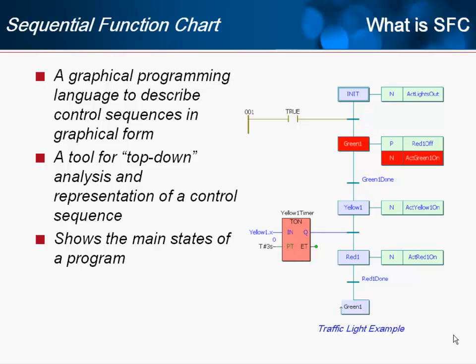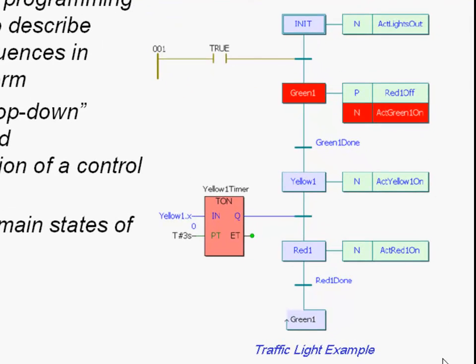You can see over here on the right, we have some SFC code for a traffic light controller. And so once you know that this is a traffic light controller, with SFC you really don't need to get too deep into the code to get an idea of how the program works. What part of the code is running, what state the traffic light is in.